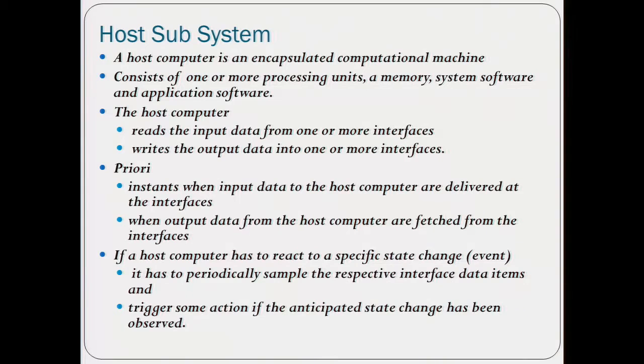Of course, if a host computer has to react to a specific state change, so an event that has occurred, for example, in the sensor, so you read something new, then what does it do? It has to periodically sample the interface, right? And that period is the TDMA period, right? So it has to look at this input buffer and trigger some action if indeed that data that is contained in its read interface contains something that tells you to do something, right? Sometimes the data are irrelevant and they are left there and you don't do anything with them and you overwrite them. But if it contains some important information, you wake up and do the appropriate operation.